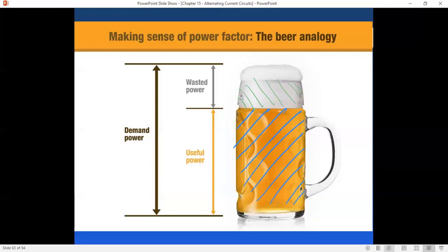So again, these inductive loads can bring down the grid, even when the grid has enough capacity to power everybody. What happens again is the phase between the voltage and the current becomes further and further away, and this can do damage to our substations. This can do damage to the generators, and this is why we tend to have blackouts, because the power company has to shut down different elements of the grid.